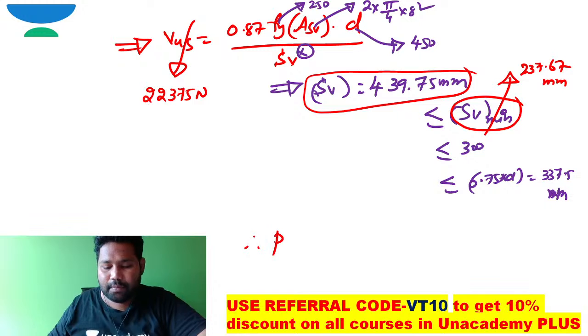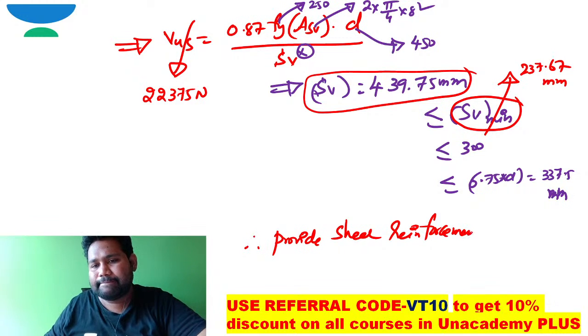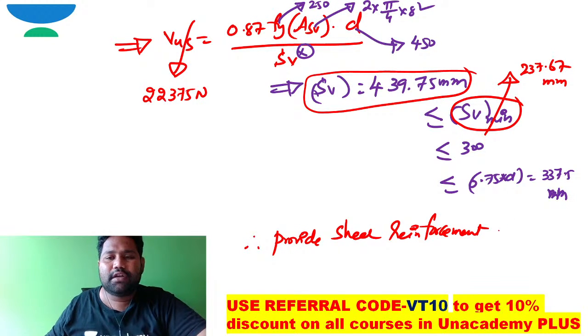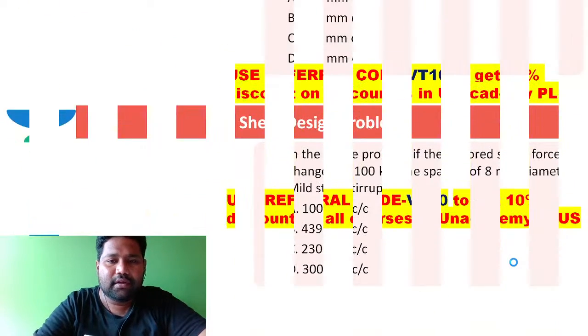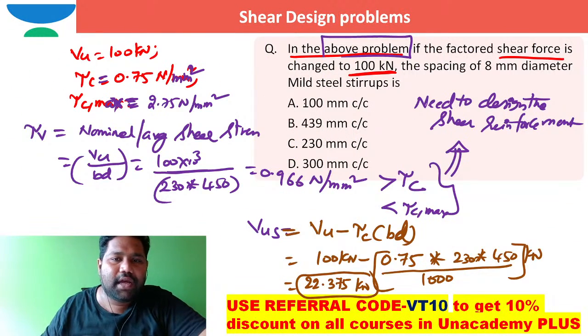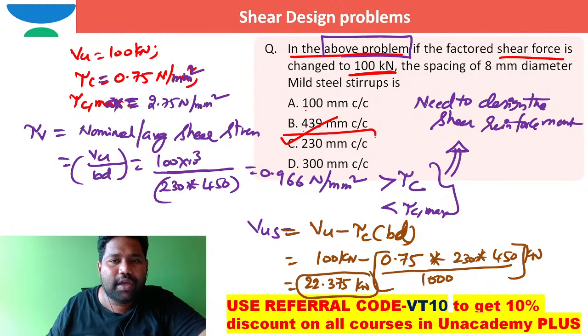So definitely you need to provide shear reinforcement with spacing 237 millimeter. If I go to the options here in this question, options are 100, 439 is also there. This we got by equation, but you should not pick this one. 230, 300 is there. So the correct option is less than or equal to 237. Nearest option is 230 millimeter. You can pick this option.